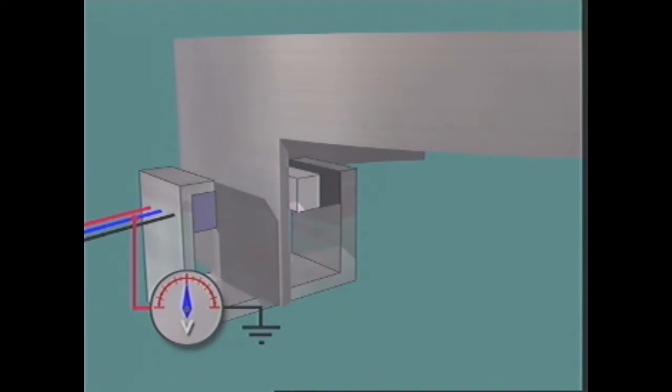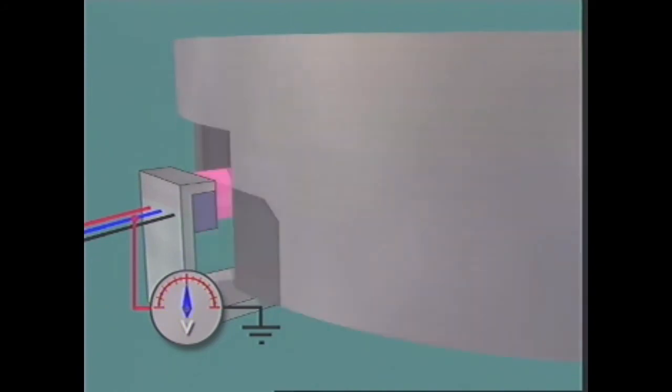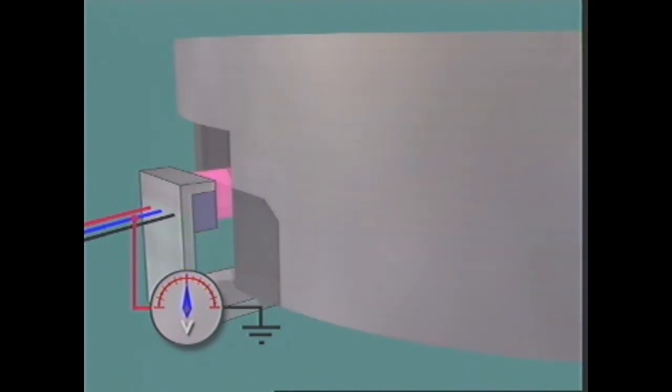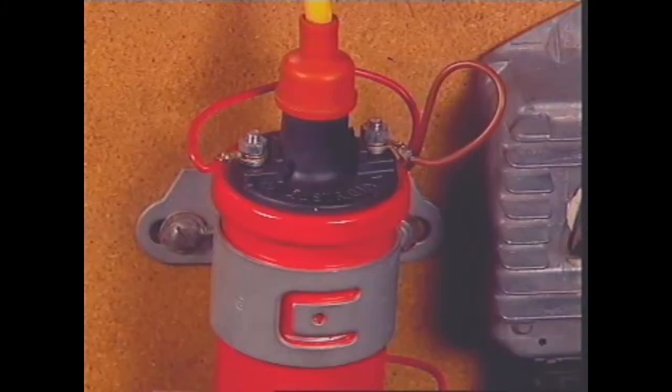With continuous rotation, the blades repeatedly move in the air gap and the signal voltage will appear to turn on and off repeatedly. This can be used to control the operation of the ignition coil primary circuit.